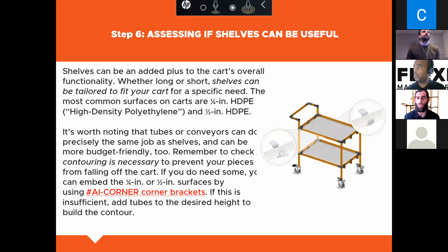When installing surfaces, we think about using 2 different methods. One is installing or securing it from the top, using a screw to secure the HDPE through the pipe. Or we also think about securing it from the underside of the structure. This way we use an AOEMT or a pipe clamp that can be placed onto the shelf, onto the pipe, and then we'll fix it with the screw on the underside of the shelf. So those are 2 different ways, very commonly used.